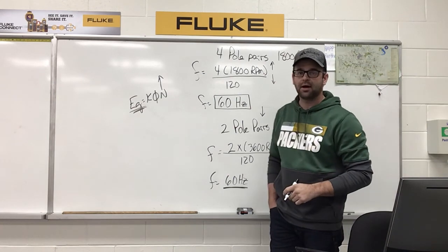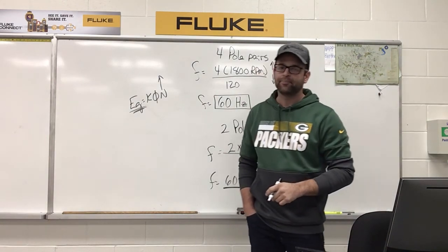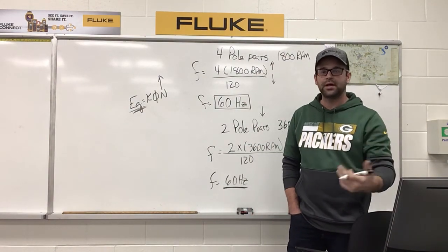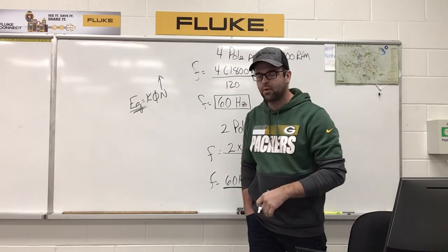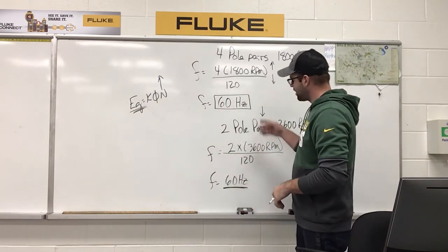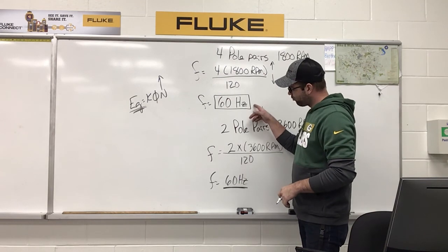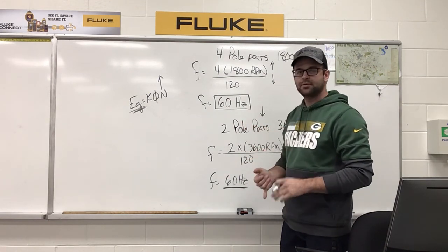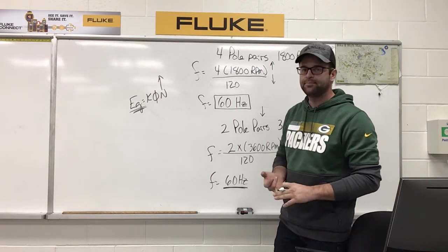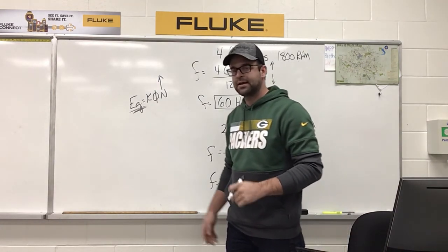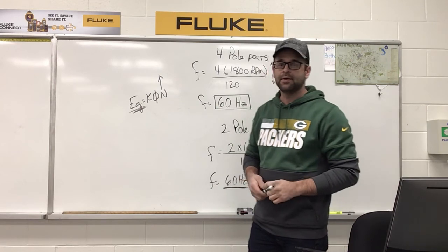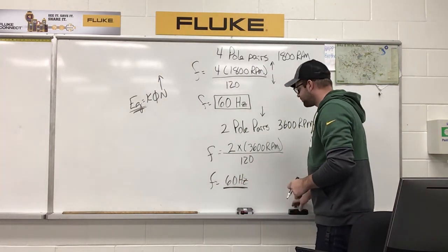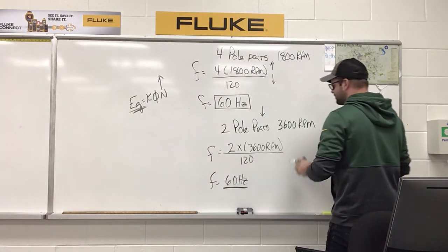So speed is not a determining factor. It's obviously the relationship between the RPMs and also the poles that gives us the frequency that we have. So frequency was more that determining factor when paralleling, so it was voltage, we had a frequency, and then the other two were the in-phase opposition and the same phase rotation. Okay, so that's fairly straightforward.